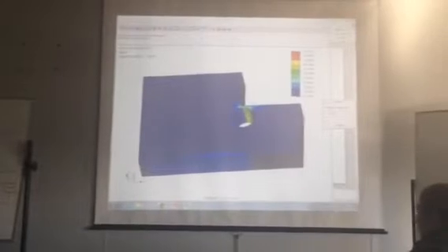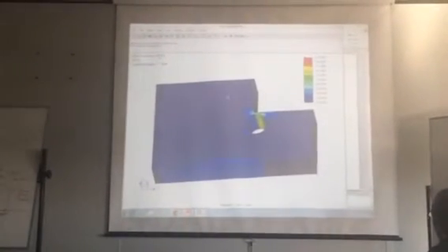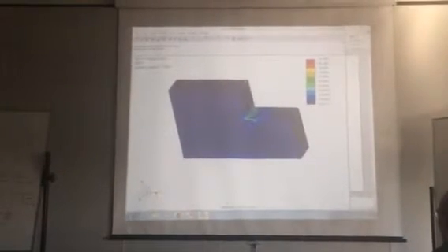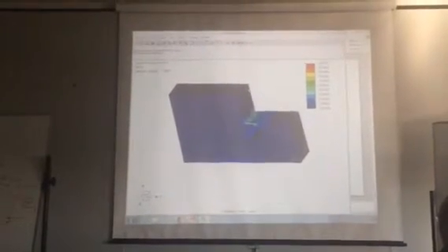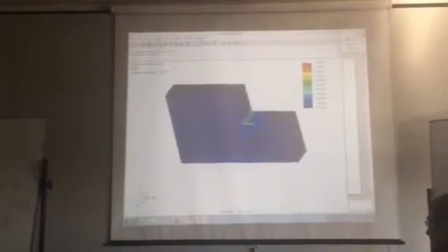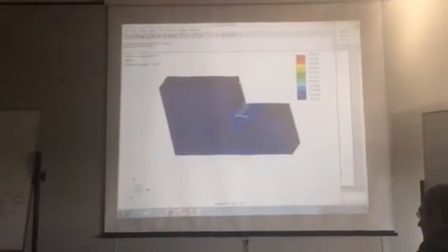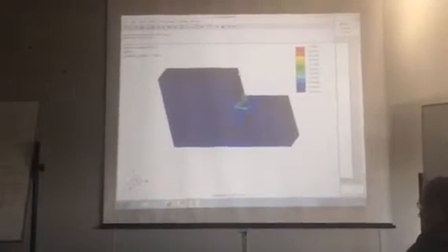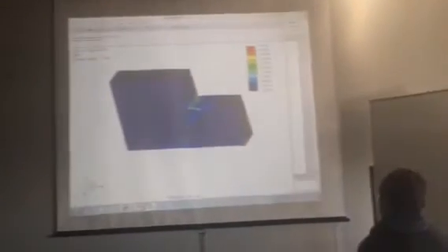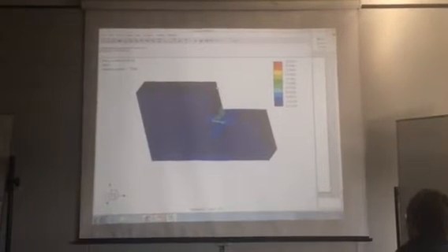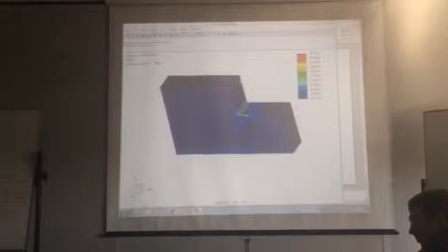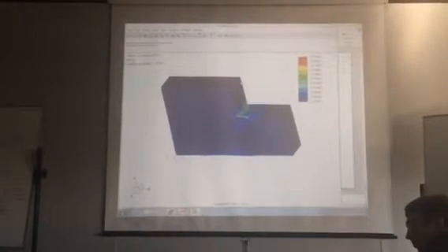So that's what we use this for. We're also interested in deflection, because the deflection is a whole set of different equations. Stress is one thing and deflection is a separate thing. As you've heard me saying before, if you think about something like a diving board, you want loads of deflection, and yet you don't want the thing to break, so you have to watch the stress. Sometimes you're interested in deflection. Mostly, if you're doing a beam in a roof, the deflection is the criteria that's the problem, not the stress, because you don't want a beam that's going to bend, because it's going to crack all your ceiling.